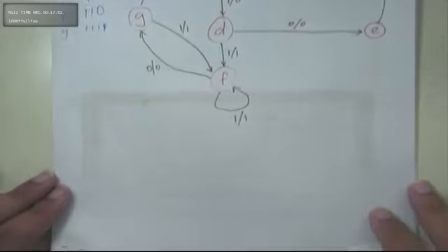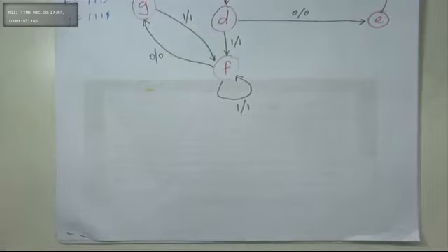All right. So I'm going to do a reduced state table, just to save space and save time. Do you have a system input over here? By looking at the state diagram, is there a system input? Yes, there is a system input. Is there present state? Yes, present state will have how many columns? 3. Right? So on the input side of our state table, there will be 4 columns, right? Then next state. Is there a next state? Yes, there is. How many next states? 3 next states, 3 columns. Is there a system output? Yes, there is a system output. So X and Y, I guess. All right? Okay. So that's your full-on state table, right?